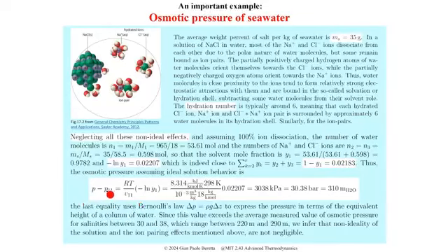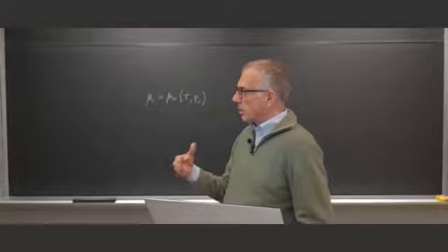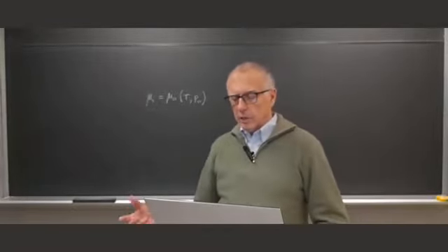And we can compute, therefore, the osmotic pressure using Van't Hoff. R T, I assume 298, just to put a number here. The specific volume, here it is correct, is with a double I, the specific volume of pure water. So it's 10 to the minus 3 cubic meters per kilogram. But since we need it in moles, we have to multiply by the molecular weight of water. And in the end, you can compute this in terms of kilopascals or bars, depending on what gives you a better feeling of how much this pressure is.